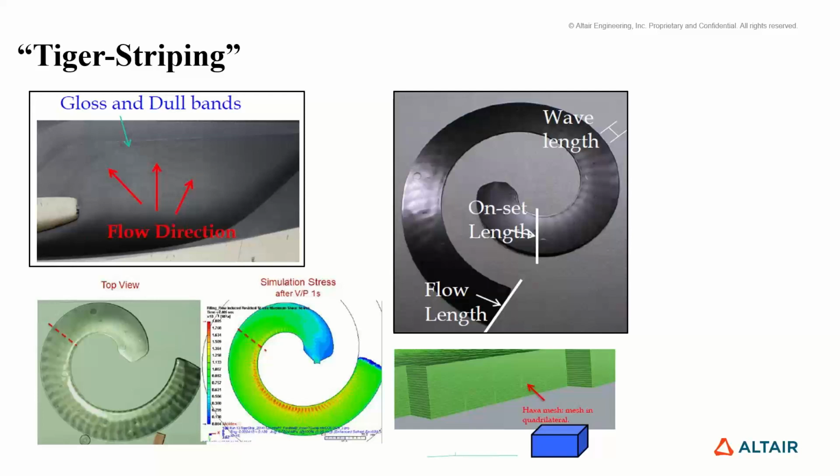And so when you see tiger striping, it should occur to you that the repetition is very cyclic. You have some kind of cyclic behavior going on. And typically, I look at this part as they show it in here, this effect isn't on one side, not the other. It's all the way across. It's the air. And so I look at this as the air going in there: clean the vents, and that problem tends to go away almost 100% of the time, unless there weren't enough vents to begin with. So that's it for the slides in this.